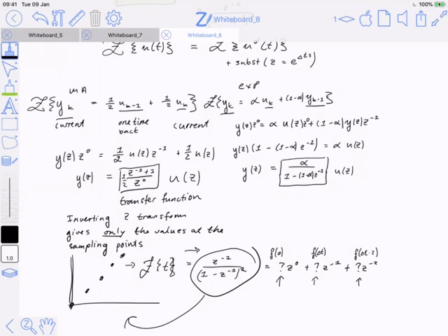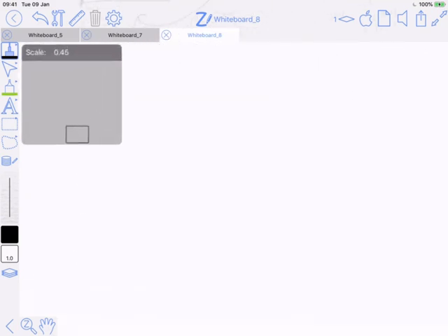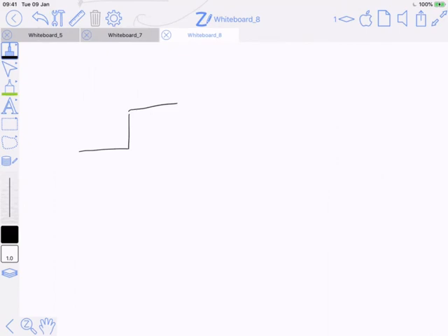I want you to be able to find the Z transform of a given signal. Understand that this means that, just like in the Laplace transform, you may need to build the signal that I give you from these basics, right? The same thing holds. If I give you a shape like this, you're going to say, oh, wait, that looks like 2 steps, one after the other. And so you don't have to reanalyze that specifically. You can use the same techniques that you used before with your continuous inputs, identify that as 2 steps added together, and then just use the step Z transform.